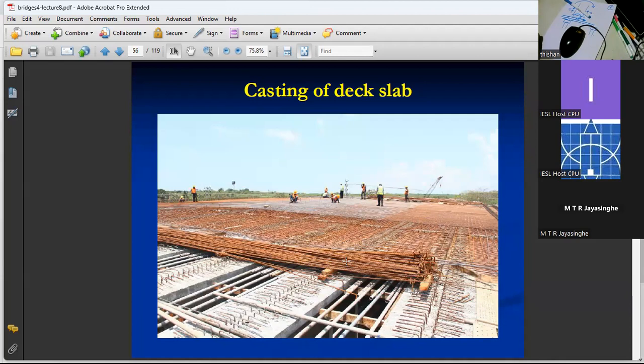But most of the other highway loading may not be that significant. And even in that case, you need a kind of traffic jam on one side of the deck, because these are 4-lane decks. So on one side, 2 lanes are full of traffic, the other side is empty. That type of situation would be needed.